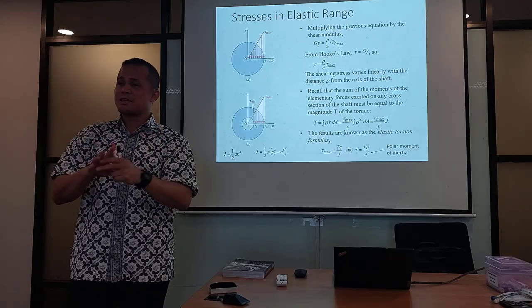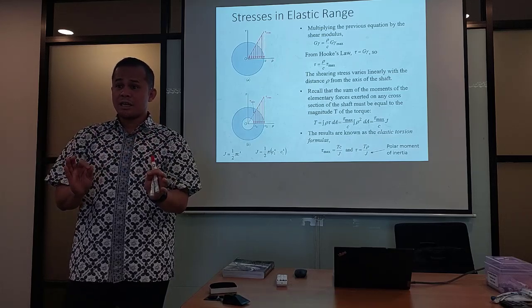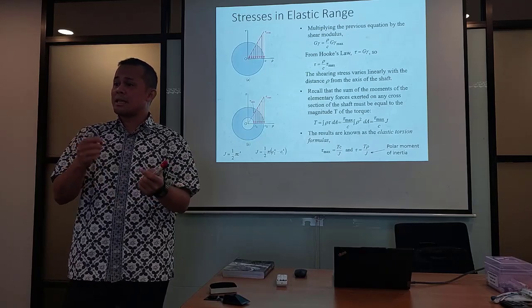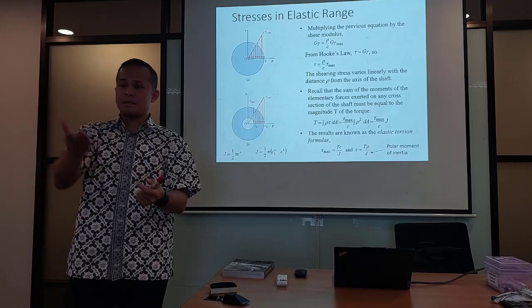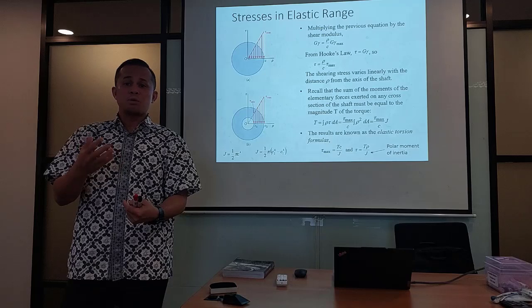and then we would like to compare it with the allowable stress. If it is less, your shaft is fine. If it is more, your shaft is in danger. It can break, it can crack anytime because it has exceeded the limit, the allowable limit of the safety strength.